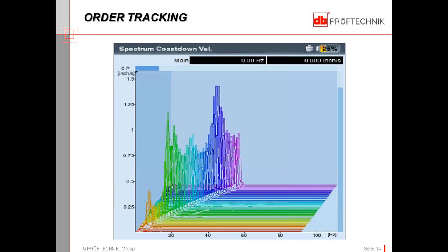And the data, as we see illustrated here, is plotted as the classic waterfall plot. Again, amplitude on the y-axis, frequency on the x-axis, and RPM on the z-axis here, not labeled, but this would be RPM. So, lovely technique.